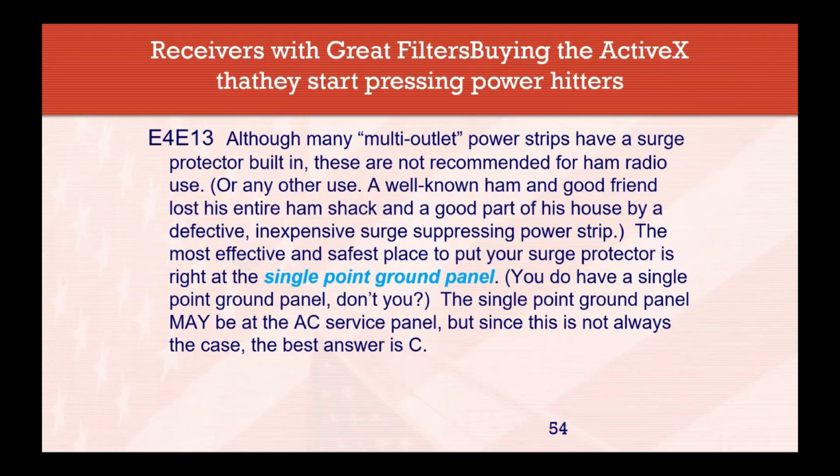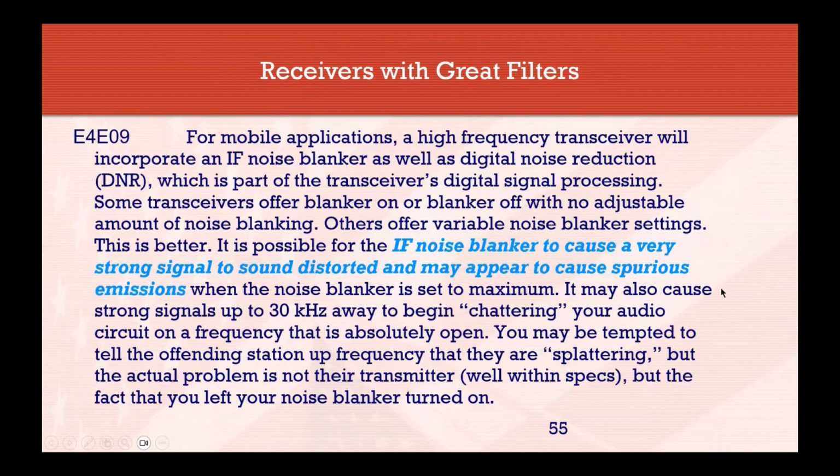Multi-outlet power strips should be placed at the single point ground panel. That is, you should have in your shack a place where everything comes together at a single point and the grounds all emanate from that point. So your surge protector should be there.